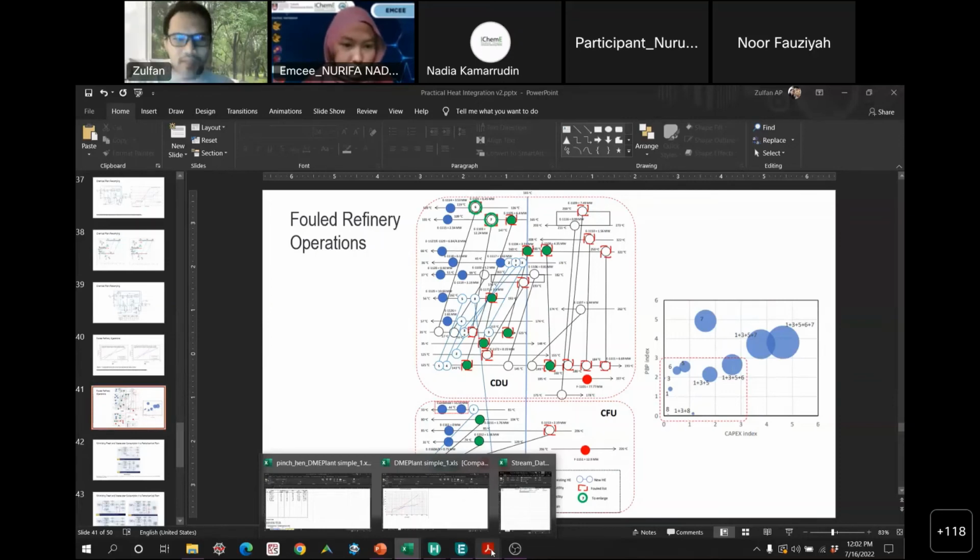So they need to put a label, because that's part of the job, so that they know which exchanger to focus on more for cleaning and maintenance. They don't do any of these U value calculations that I mentioned before. They simply see it during the turnaround, and they know: fouling, no fouling, fouling, no fouling. That's the practical way.